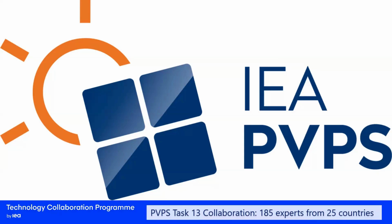I just think if you're trying to analyze the effects of the east and west side, you really should have two, one on the east, one on the west. Because typically for bifacial, it's the tracker side that's closer to the sky that will get more irradiance than the side closer to the ground. So if you have just one on the torque tube, that won't really show you that.